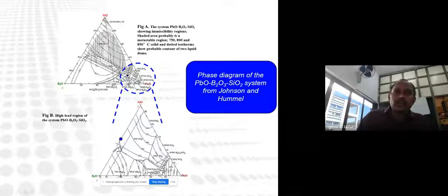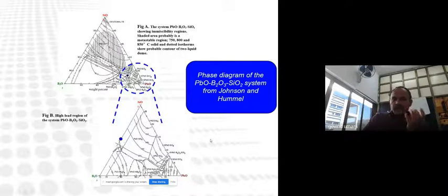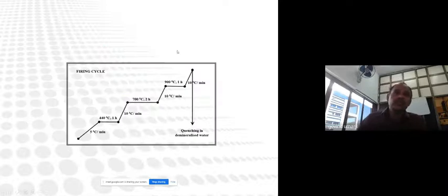In this case, we have selected this composition because we need the glass to melt after 550 degrees Celsius, and before the softening of the nano silver powder. So this is the protocol we optimized for synthesizing our glass powder, and at 1000 degrees Celsius we suddenly quenched this molten mass.